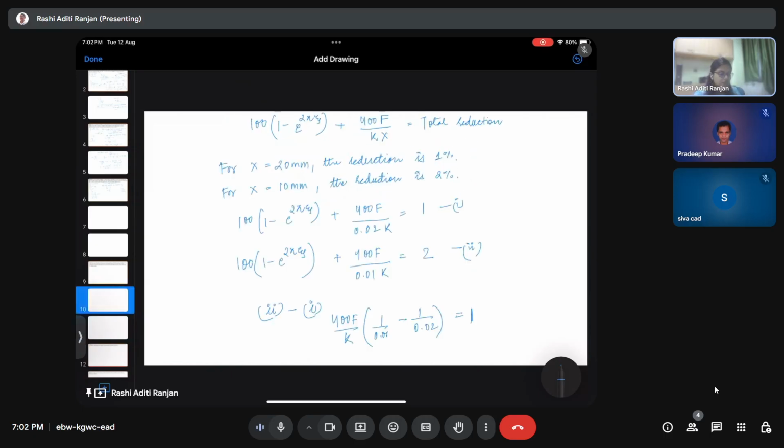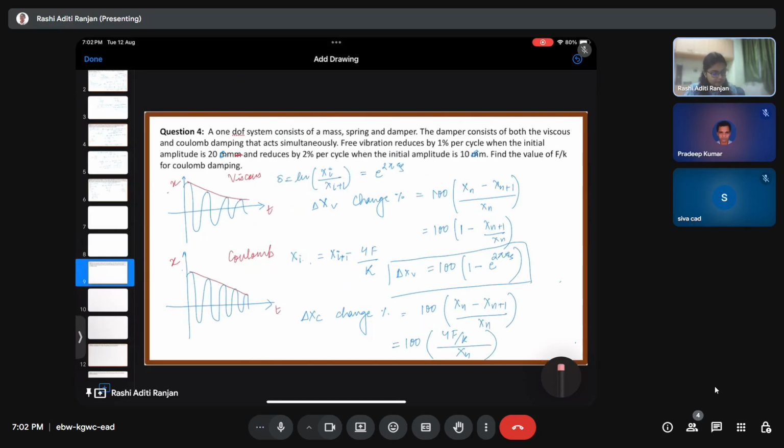You see, using this equation that we got over here, you can actually evaluate their specific contribution, or how much it has decreased because of viscous damping and how much it has decreased because of Coulomb damping. But this case, which we have used for solving this system, is applicable for a linear range, and if we consider that both are independent of each other. While in the physical case, that doesn't happen. These are actually dependent on each other. But for now, we have just taken this for the simplicity of solving this equation and using the concept of how we deal with the system if we consider both the viscous friction as well as the Coulomb. Okay. So I hope that this is clear.